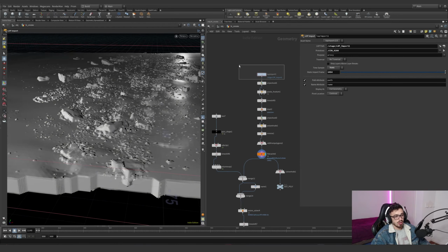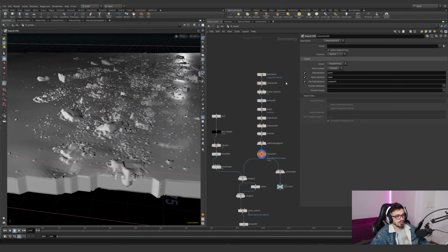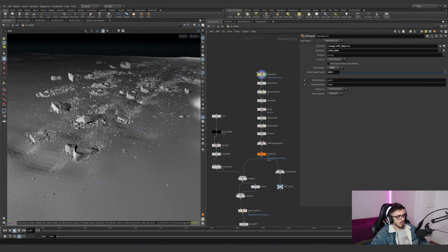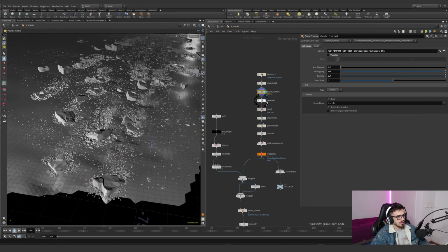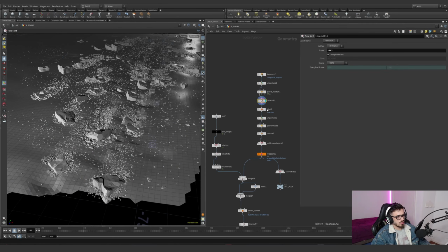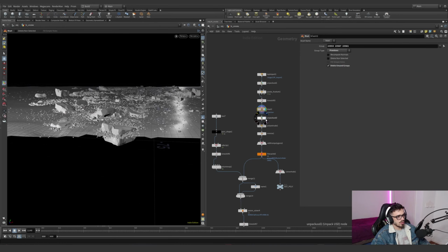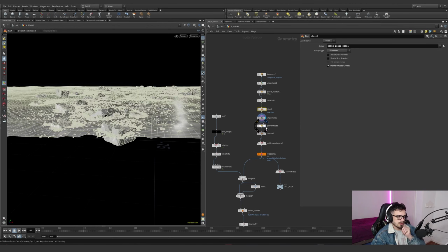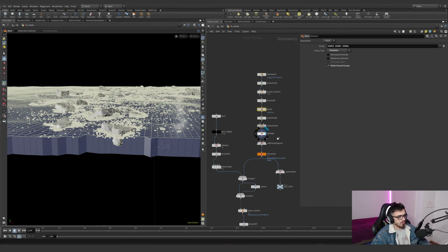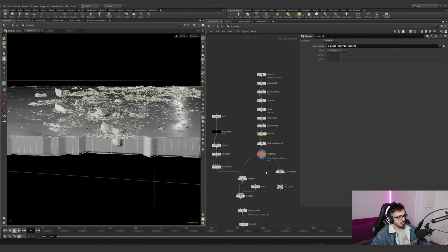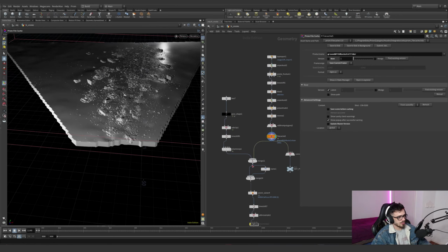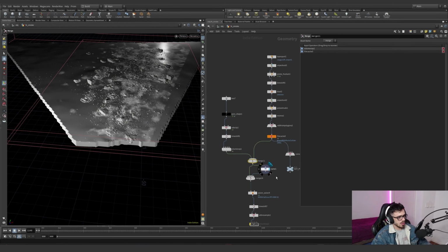I'm going to show you later in this video how this was done, but it's just, I'm getting this geometry, I'm unpacking it, I'm freezing everything that I don't need, I'm shifting this because this is animated, and I'm blasting the points that I don't want. I'm unpacking this. This is the longest process because there's a lot of rocks. I'm poly extruding the ground, reversing the ground, VDB from polygons, and saving this to this. So this is my collider, merging these two guys together, and then saying, hey,